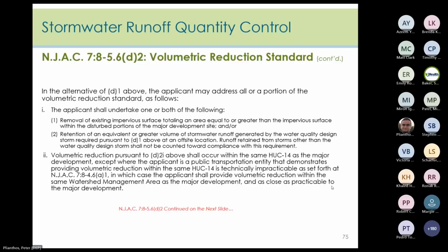Additionally, the volumetric reduction must occur within the same hydrologic unit code 14, or HUC 14, as the major development. However, if the applicant is a public transportation entity and can demonstrate that providing volumetric reduction within the same HUC 14 is technically impracticable, they may instead provide the reduction within the same watershed management area and as close as practicable to the major development.